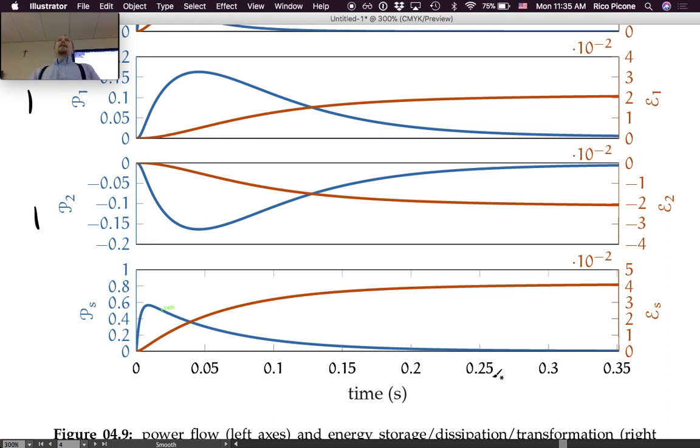So that's why we looked at all the variables in our output, is that we wanted to see all these things. We're kind of interested to see. So now, you guys are going to go in the lab and you're going to be like, okay, I remember that the power is being dissipated. The dissipation power early is quite a bit because of the resistive element, but then it's going to go to 0 when it's in steady state, whereas the damper one is going to increase steadily, etc. So hopefully you guys have a feel for it now.